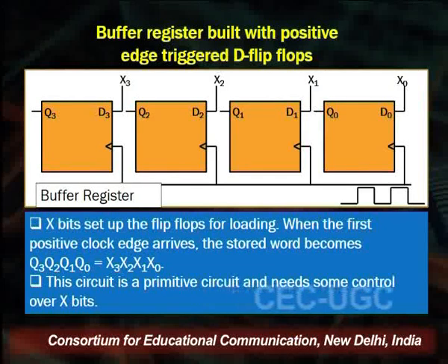So we understand that there are only 2 input combinations wherein S and R are not equal. That is 0, 1 and 1, 0. So the D flip-flop is a modified SR flip-flop with only 1 input that ensures that S and R are always complements of one another.